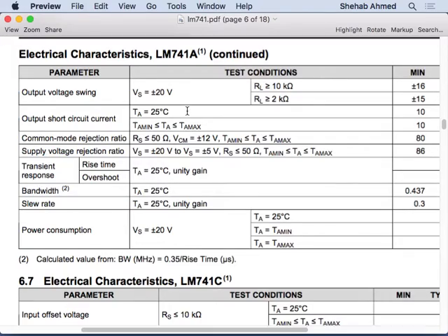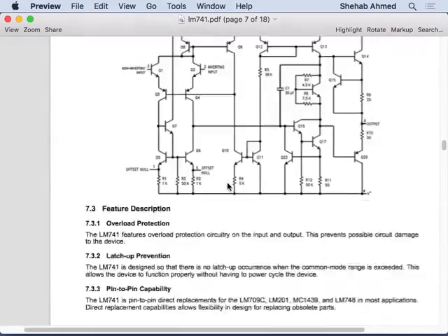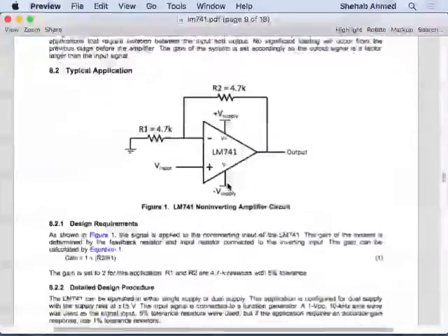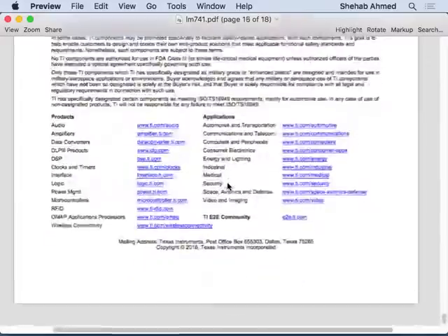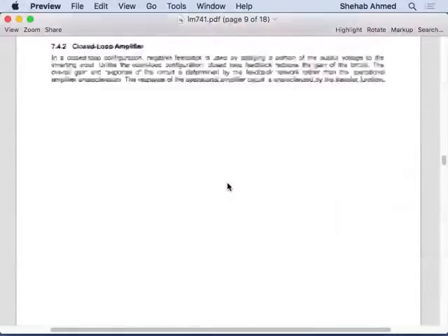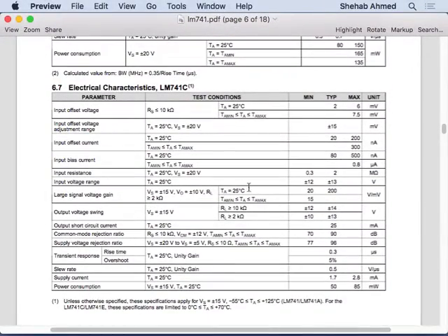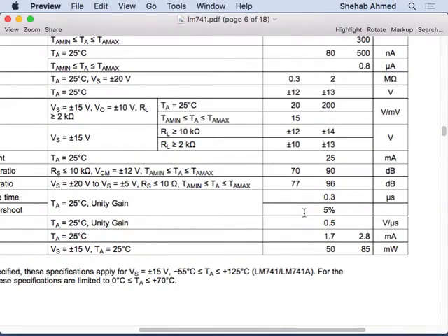So if you look at the textbook, let's see if they have the gain plots here in the datasheet. Maybe they will. They don't have the gain plots, frequency dependent gain plots. But in the textbook, they tell us that these op-amps have a limited high gain bandwidth, or limited high gain frequency, meaning the break frequency is very low. They're telling us that. And for the 741, they told us it's at 10 hertz, right?